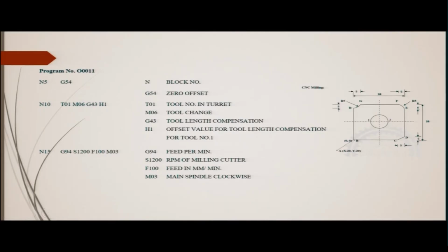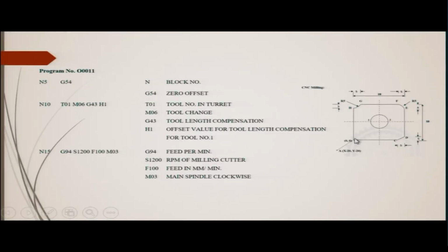This is something which I have to explain to you. It was not there in the case of turning, that is, the tool in this case is a milling cutter. In the case of turning, it was a single point turning tool, so the tool point was exactly touching the workpiece. In this case, the milling cutter has a diameter, and all the movements of the milling cutter along the profile, for example, the milling cutter will move from B to C, then here and so on.